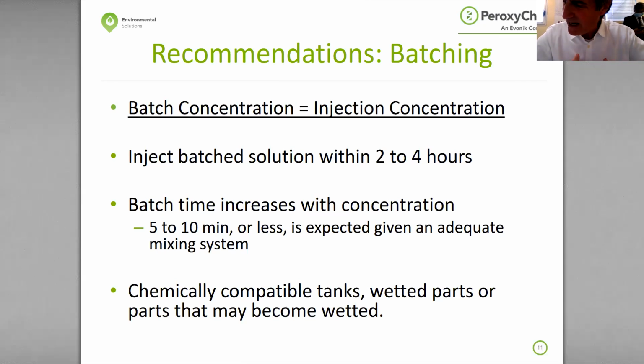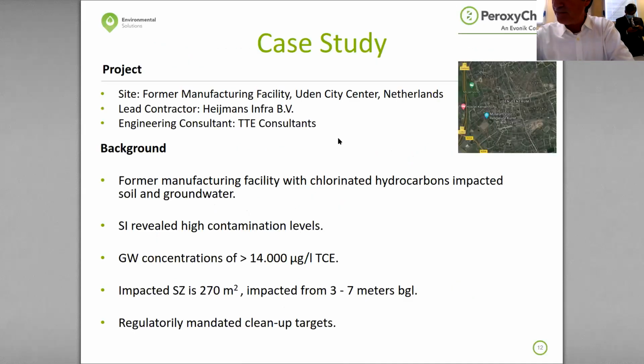In terms of the time it takes to dissolve the product, since all of the components are highly soluble, they dissolve quickly. We expect a 5 to 10 minute time frame, with lower concentrations generally requiring less time and higher concentrations a little longer. It really depends on how good of a mixing system you have. And of course, even with the appropriate mixing and batching systems, chemically compatible equipment is recommended. Tanks, pumps, gaskets, pressure valves, flow meters, and any wetted parts should be chemically compatible.